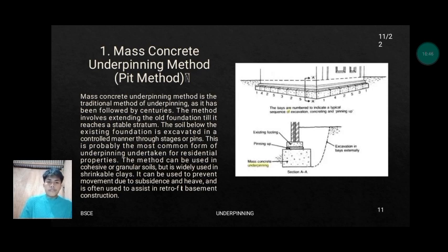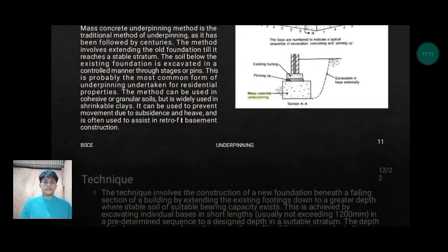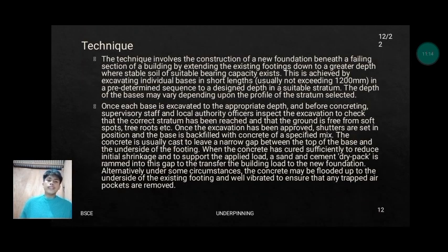It can be used to prevent movement due to subsidence and heave, and is often used to assist retrofit basement construction. And here are sample pictures of the mass concrete underpinning method, or pit method. So what are the techniques involved with the mass or pit method?